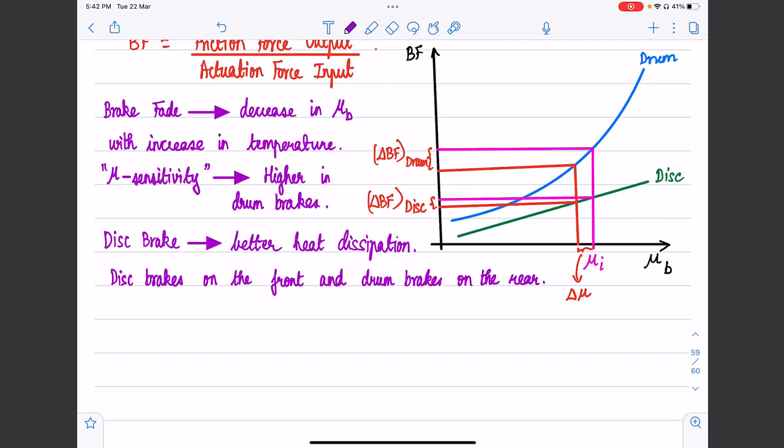Sir, when the braking is usually done, the weight of the vehicle comes to the front. When the weight transfer happens to the front axle, the reaction on the front wheels will go up. So they will tend to slip less than the ones in the rear end. Okay, fine, very good. We are going to do that analysis, and then we will build more on that argument. But that's a good point.